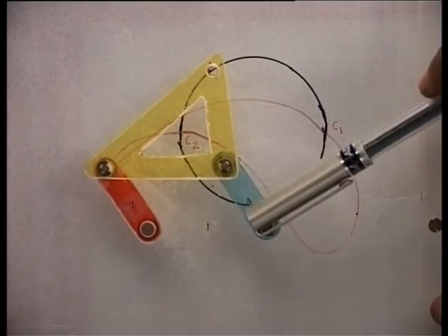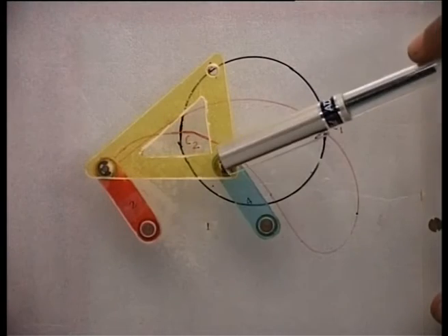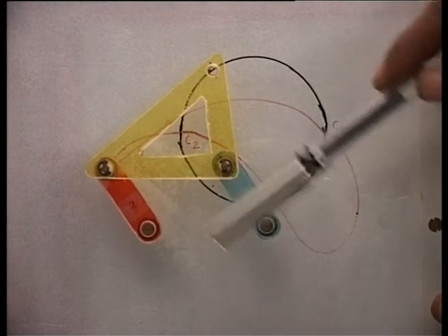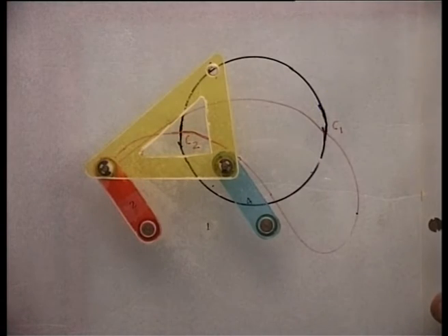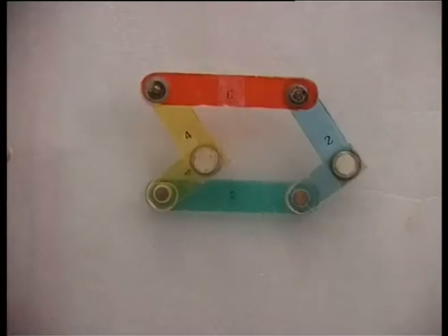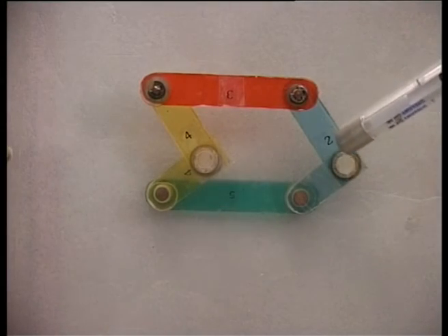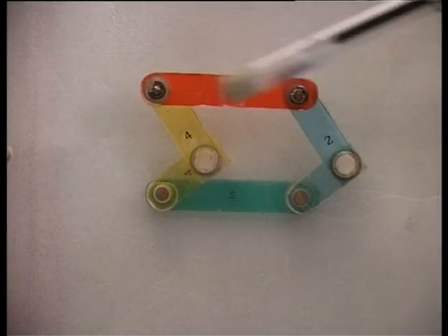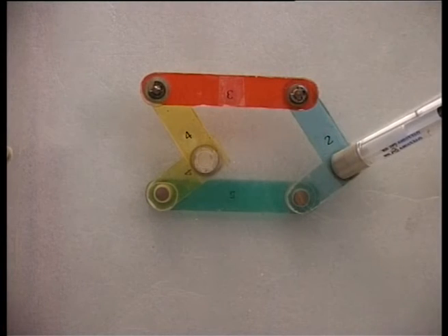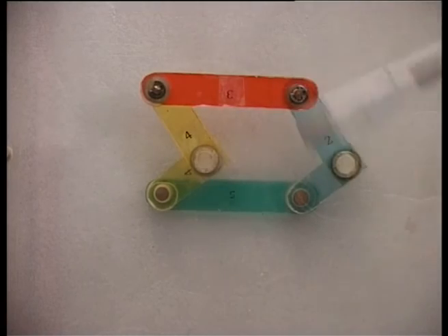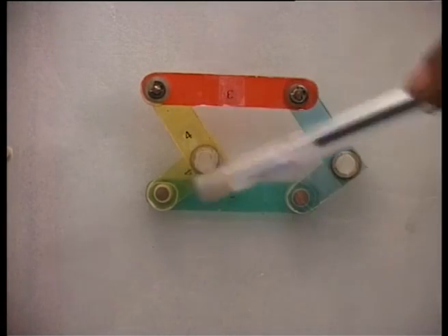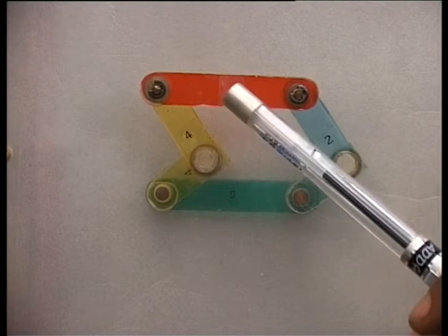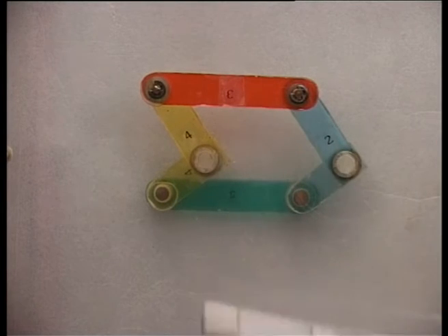Thus, to overcome this uncertainty configuration in a parallelogram linkage, we can use an extra coupler, a redundant coupler, which we have seen earlier, and I will show it to you again. Let us again look at this parallelogram linkage where this length is equal to this length and this coupler length is equal to the frame length. So, this is a parallelogram linkage. However, this parallelogram linkage has a redundant or extra coupler which is of same length as this original coupler.